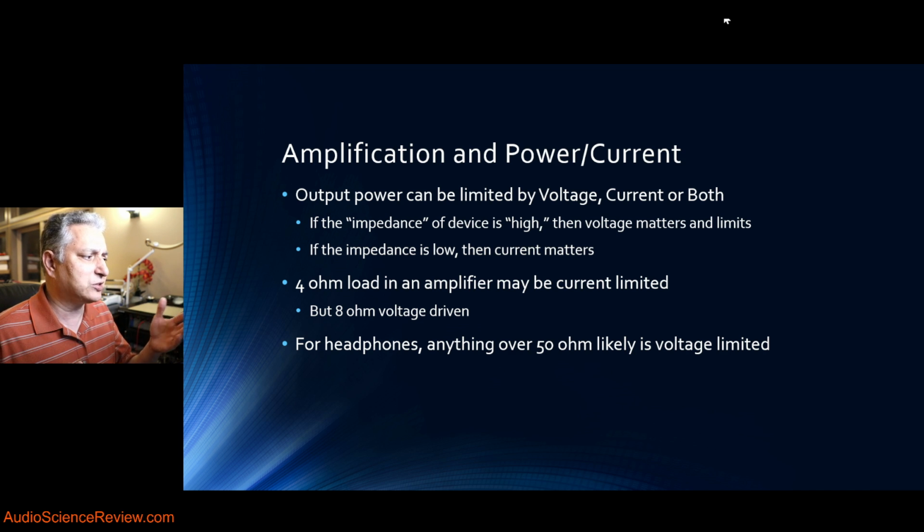Okay, so for this reason, when I do my headphone amplifier testing, I show 32 ohm, and I also show 300 ohm. So one emphasizes voltage, the other one emphasizes current.